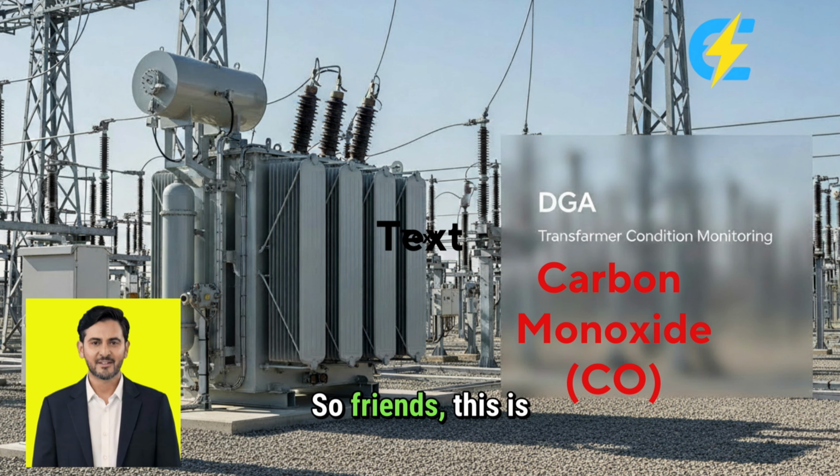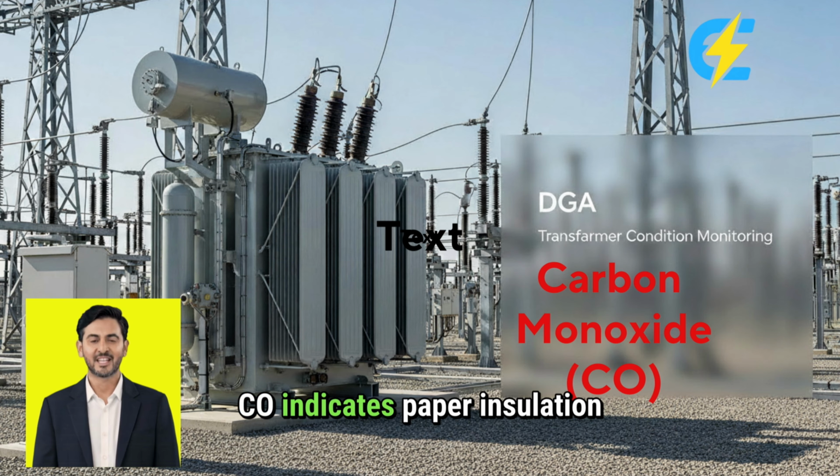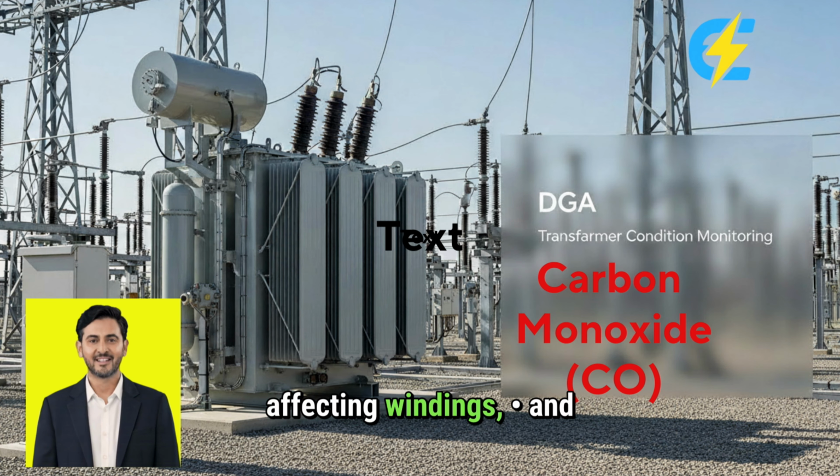So friends, this is the real meaning of carbon monoxide in DGA. CO does not indicate arcing. CO does not indicate oil cracking. CO indicates paper insulation degradation. It tells you cellulose is breaking down. Thermal stress is affecting windings and insulation. Life is being consumed.